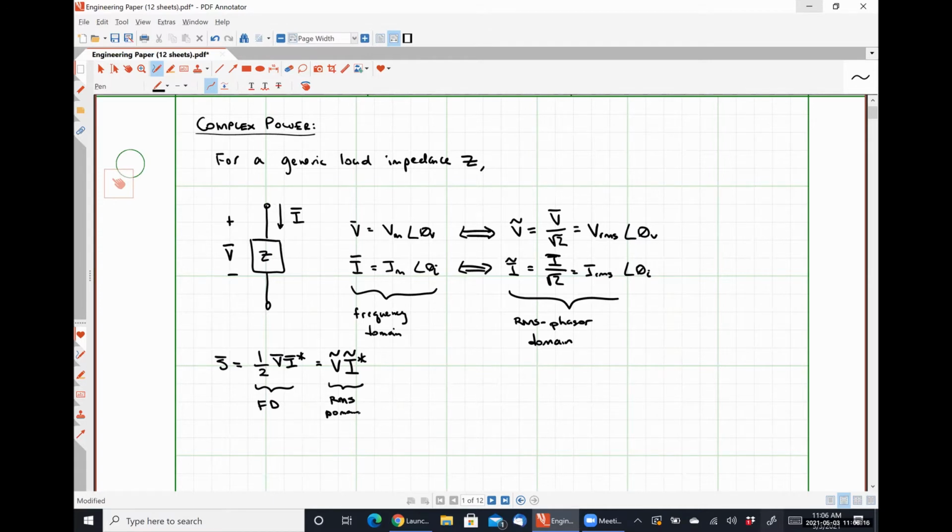Since complex power is the product of a voltage and current, it should seem like complex power should be measured in watts. However, that would be arbitrarily confusing, okay? So power engineers developed their own unit for this specific quantity, and it is called the volt ampere. So the volt ampere is the unit of complex power. Dimensionally, it is identical to a watt, but if you're talking to another electrical engineer and he mentions something in volt amps or VA, that means that he's specifically talking about complex power or apparent power, which is the magnitude of complex power, and we'll be talking about that shortly. So right now, we are treating S as a complex number, which has obviously some magnitude and phase angle. Sometimes we only care about the magnitude, but that's obviously just going to have the same units.